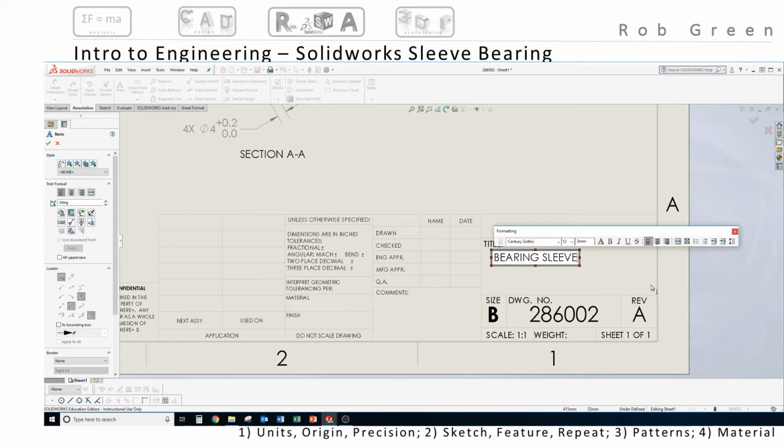In all of our drawing title naming, not necessarily software file names, but in our drawing names, we always want to progress from the most generic to the most specific portion of the name. So the fact that it's a sleeve is a subcategory of bearing. Notice there's things called ball bearings, thrust bearings, needle bearings. They would all be titled bearing needle, bearing ball, in that order.